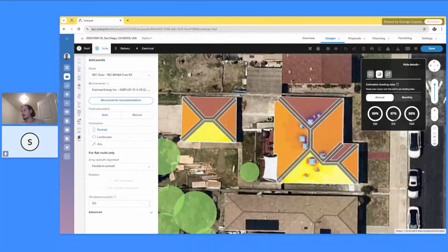The other thing we look at is called the tilt and orientation factor. And again, that's a percentage, and it describes how optimal is this roof facet compared with ideal conditions, given its tilt, so its angle with the ground, and its orientation. So in the Northern Hemisphere, where I am, south-facing roofs will produce more energy than north-facing roofs. So due south, 180 degrees, that's 100% for the orientation factor.